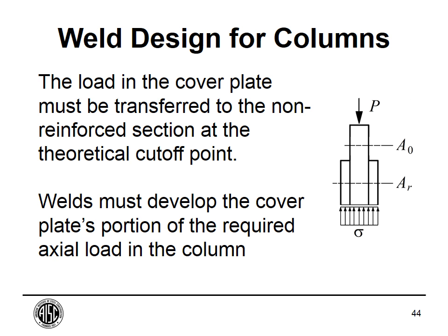Let's say our reinforcement cuts off short of the top of the column like I've got shown, and maybe our theoretical cutoff point is at this point. So whatever proportion of the load is in your plate, this stress, has to be developed over this length, which is the development length.